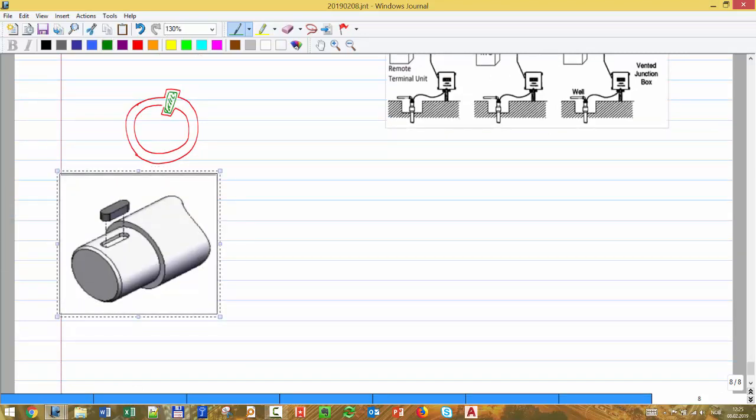Okay, and also note something else. That means it's not really holding the weight of the impeller. This is simply passing through, and when it rotates, it makes it rotate. But the weight is not being held by the axis. It's actually able to move in the vertical direction. That means the weight is going to be held by, if you see here, it has an annular space, and you see here it has also the same annular space made, such that it's held by that.